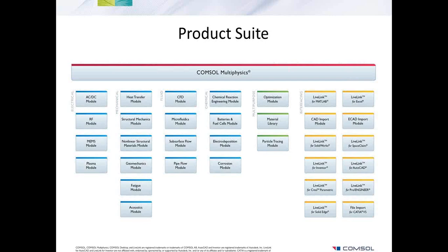Sarif here wants to know, why did you apply a fixed constraint to the tail mass? You can say that's an arbitrary choice. The idea here is that we are holding the transducer somewhere. It's not just floating in water. That's not typically what it would do. So it's definitely being held to the structure somewhere, and we are just modeling that as a perfect attachment. So the fixed constraint works something like a perfect attachment to something else.